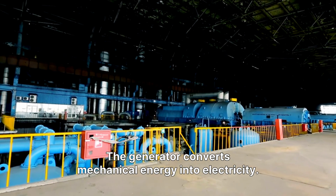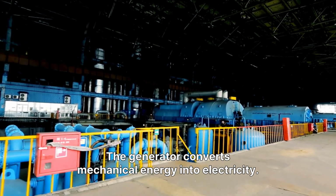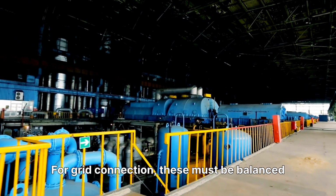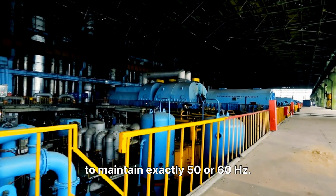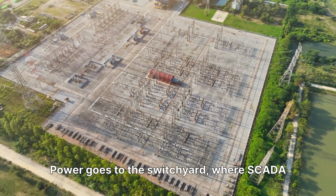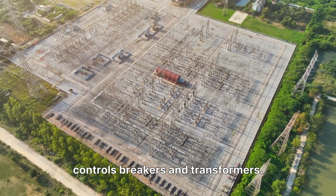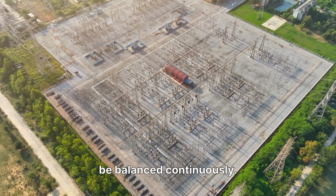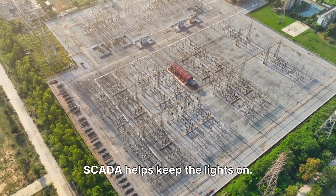The generator converts mechanical energy into electricity. SCADA monitors megawatt output and frequency. For grid connection, these must be balanced to maintain exactly 50 or 60 Hz. Power goes to the switchyard, where SCADA controls breakers and transformers. In grid systems, generation and demand must be balanced continuously. SCADA helps keep the lights on.